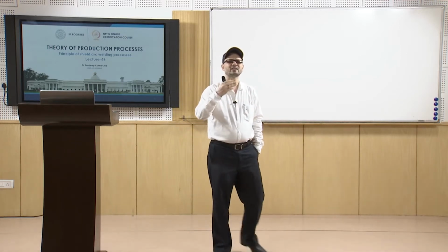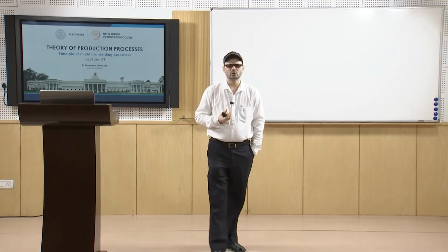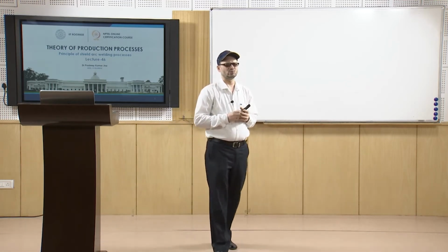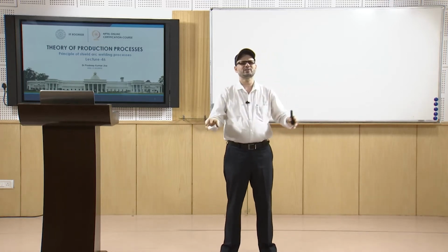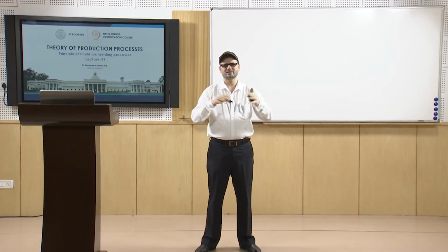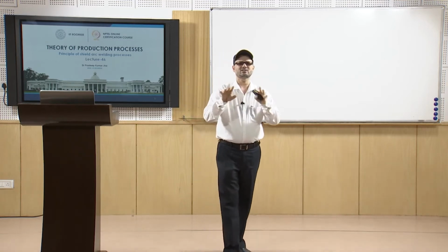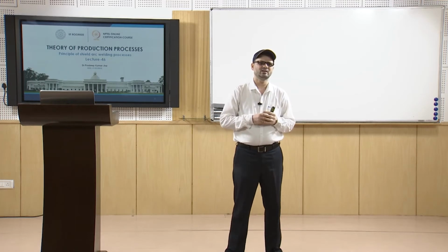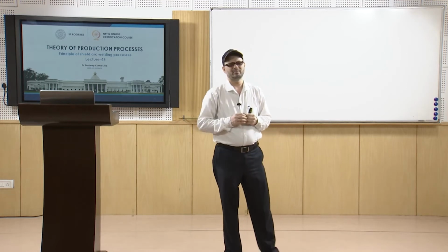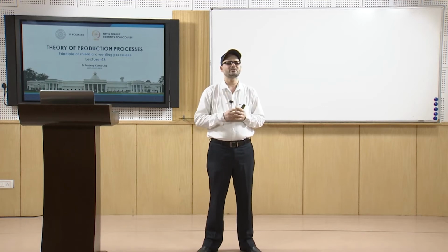Then about the shielding, sometimes we use a coating on the electrode. In that case, the coating material over the electrodes melts and creates an atmosphere around the molten pool, so they will cover it. These are fluxes; they melt and create a blanket of gases on the top surface of the molten weld pool, and this protects the weld pool. That is how shielding is done.